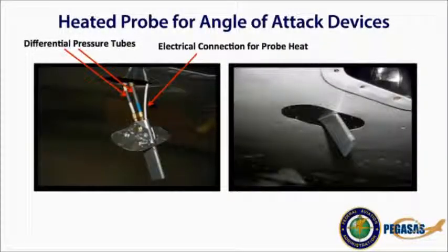Installation of the optional probe heat function requires some planning. The probe heat will require a separate switch and fuse or breaker along with the appropriate wiring for the length and amount of load carried per Advisory Circular AC 43.13-1B, Chapter 11, Section 5. The probe heat requires over 7 amps of electrical power.